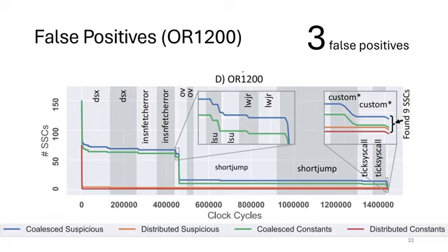So why this is different from the RISC-V one, I'm not exactly sure. It also uses a RISC instruction set, supposedly. So it's running assembly programs, and it finds 9 suspicious state-saving components, 2 of which are distributed, and those are both suspicious, and 4 of the other 7 are suspicious as well. Those were all inserted Trojans. 3 false positives were constants.